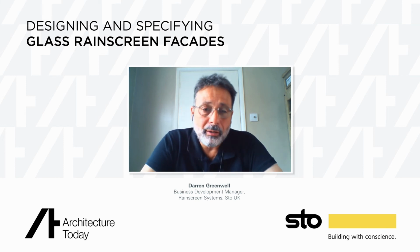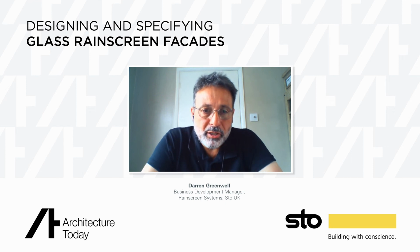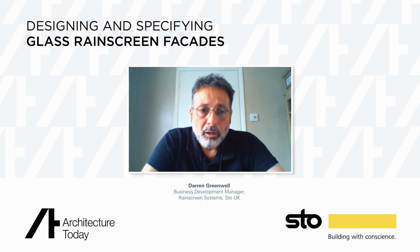I think we had a slide that demonstrated, if you were to use aluminium bracketry, the amount of insulation that you would need in order to achieve your U value, and then using stainless steel. So thermally, it's a far more stable and more efficient material. In terms of bridging, there is an element of bridging, but it's certainly negated by the insulation and the rest of the system.